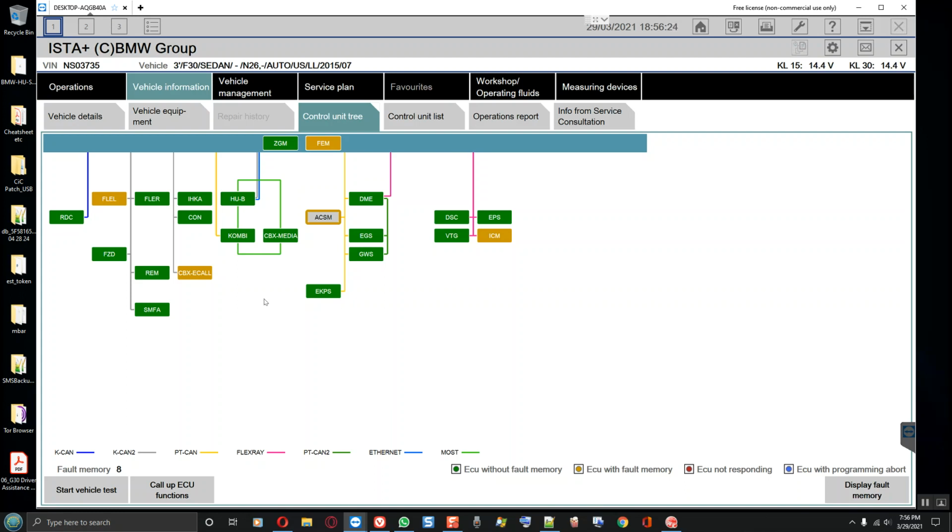Something is wrong. The study is not telling a lie, man. It's direct. Yeah, it's not getting the signal in a timely manner. When the car terminal 50 is on, it's not getting the signal from back and forth communication. So that's why it set the fault code. So it's correct. It's not telling a lie, man. Once it says the fault code is there, it's because the signals are not transmitting on the wiring in a timely manner. So, you know, the airbag light should be turned off within 4 seconds as terminal 15 is switched on.